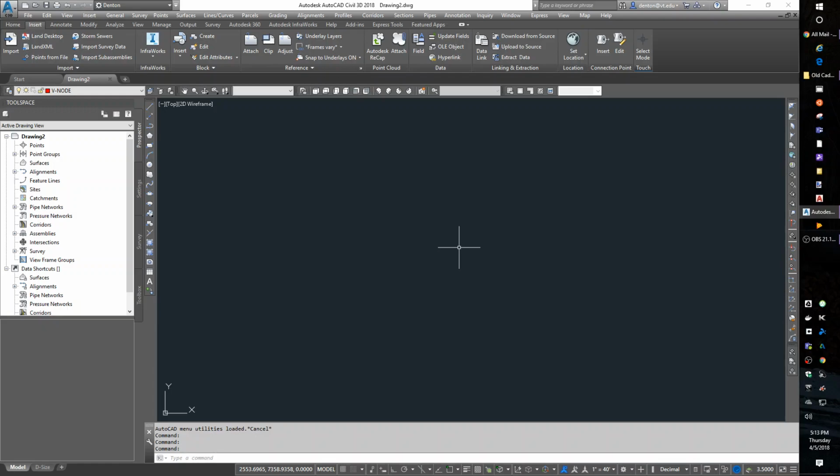And then fourthly, we will take that assembly and push it along our road at the grades of our profile to create a 3D corridor. And our 3D corridor, last of all, will let us contour it and compare the volumes of our existing ground before we did the work and after we did the work to know how much dirt we moved to do our project. So we are beginning the end right now.